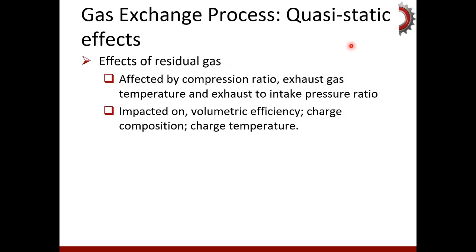Now, if you first look at the quasi-static effects, what are the quasi-static effects which influence the intake system or exhaust system for that matter? One is the residual gases. Having residual gases within the system could impact the volumetric efficiency, charge composition, as well as the charge temperature. Usually, the amount of residual gases depends on the compression ratio, exhaust gas temperature, and the intake and exhaust pressure ratio.